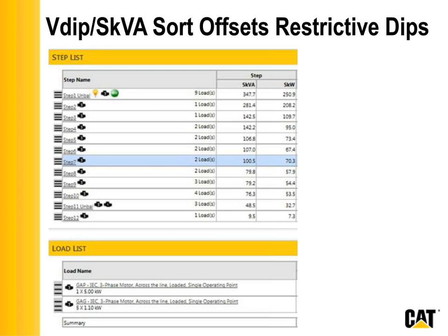I think it might be noteworthy at this point to mention that if possible, you never want to size your genset with one load step, because you'll almost always oversize your genset. So it's important to multi-sequence your load steps. Sometimes the more load steps, the merrier. But that's really what the optimizer does. It gets away from that one load step. It'll actually find the optimal number of load steps if you select optimum step. We're going to talk more about that later. But here we're just showing the Add Loads page.